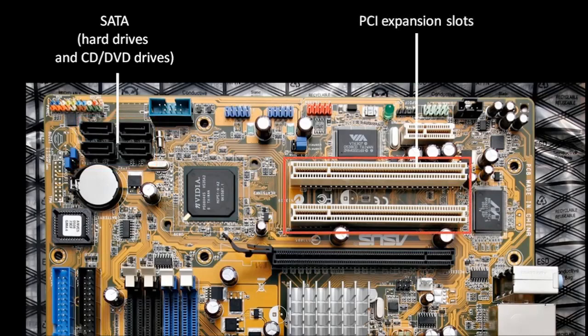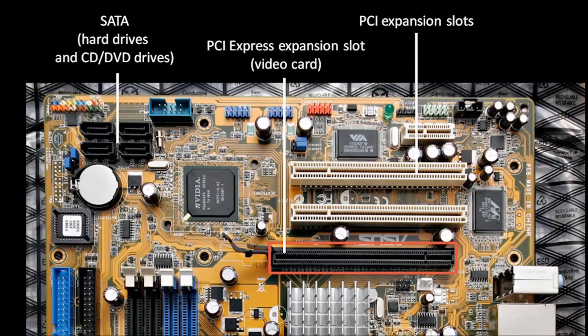And then over here on the right we have what are called expansion slots. Expansion slots are used for devices that need very, very fast connections, where it's not adequate to use some kind of cable, and so instead the circuit board itself gets connected via these metal contacts which fit into the slots here. These two slots here use the PCI standard. This black slot below uses a newer standard called PCI Express, or sometimes called PCI-X. PCI Express is a much faster kind of connection that was introduced specifically for what are called video cards, which we'll discuss in a moment.